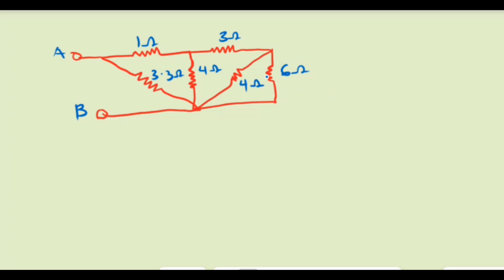So you ask yourself, these 6 and 4, are they in series or in parallel? Then you trace it here, you realize that there is a node here, then there is another node here, meaning they can't be in series, so they have to be in parallel. Then you traverse through them, and if they are the only two elements in the loop, it qualifies that our 4 ohm is parallel to our 6 ohm.